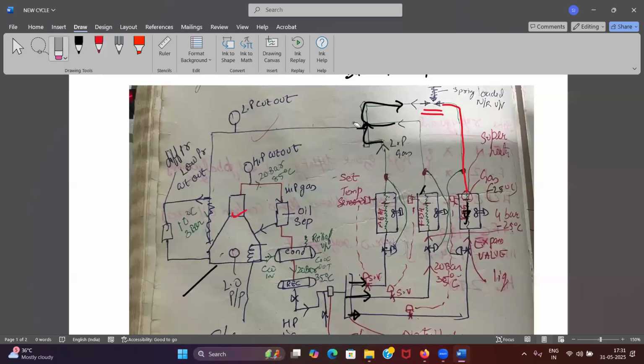So the pressure, due to the back pressure valve, in the bedroom evaporator line will be higher, right, compared to meat room and fish room. Yes. So then, sir, after the spring return, after the back pressure valve, even at that time the pressure will be higher, no? Correct, because they have to overcome it. Comparatively, yes, sir. So then, won't the pressure come in the meat room and fish room line?